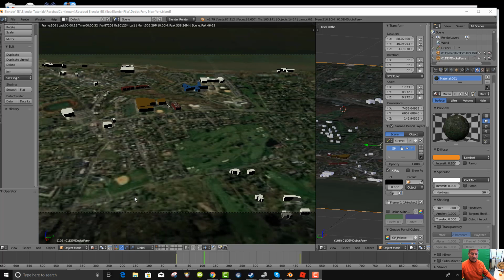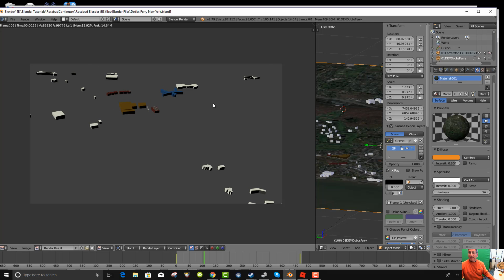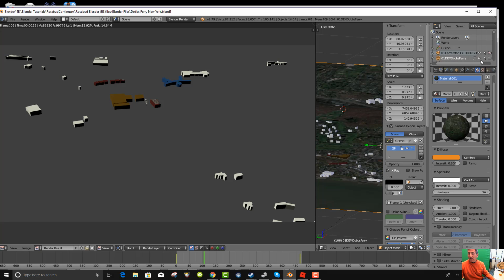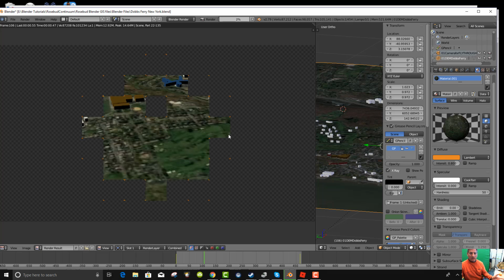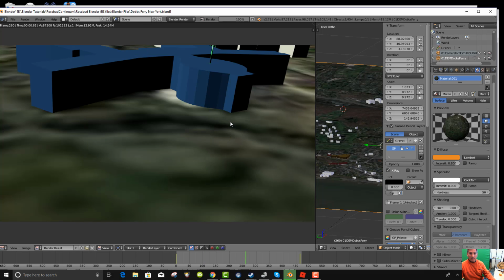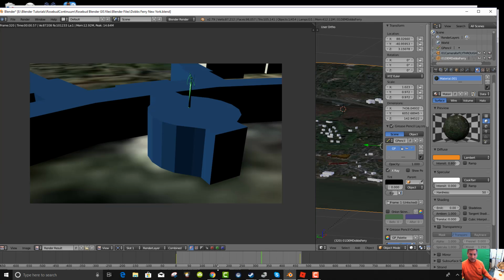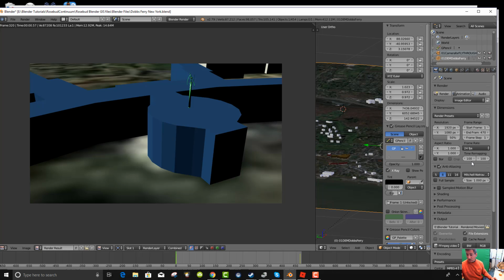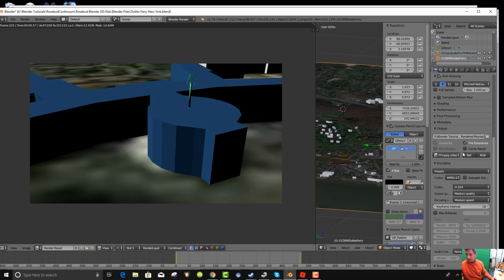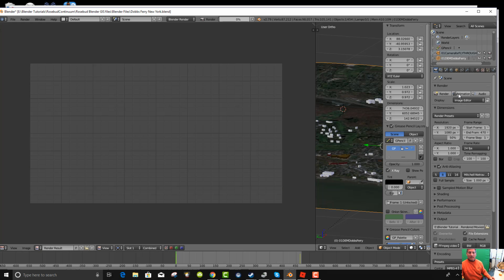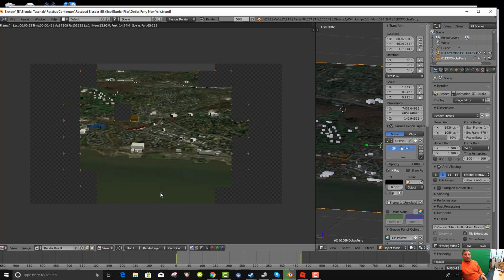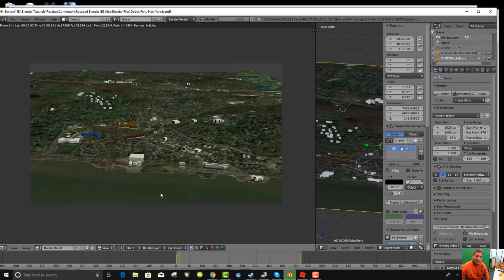Alright, so I was having problems rendering, even though when I looked at the rendered, I saw the rendered version. When I actually went to do the rendering and I would hit F12, I would just see the houses. And I didn't know why that was. And then I realized it's because my digital elevation map here had the rendering thing by default off. So if I turn this camera on, and now I hit F12, now I can render any of the aspects here. And so now I can do the animation by going to that camera that I showed, make sure that it's going to the right folder and that you've set everything correctly, and then you hit animation and it starts rendering, and it'll hopefully do the whole movie, and we'll render that out.